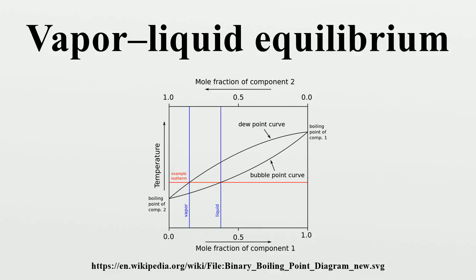The mole fraction of each component would correspond to where a point lies along a line starting at that component's corner and perpendicular to the opposite edge. The bubble point and dew point data would become curved surfaces inside a triangular prism, which connect the three boiling points on the vertical temperature axis. Each face of this triangular prism would represent a two-dimensional boiling point diagram for the corresponding binary mixture. Due to their three-dimensional complexity, such boiling point diagrams are rarely seen.